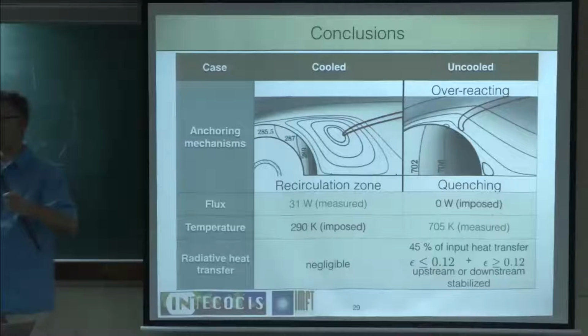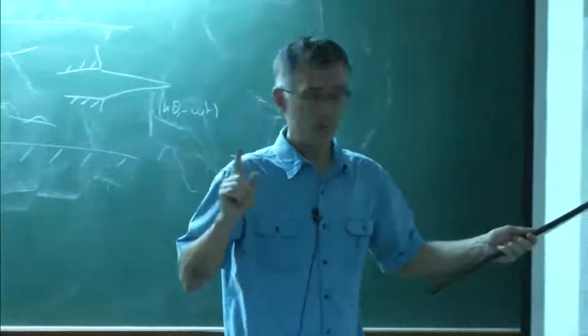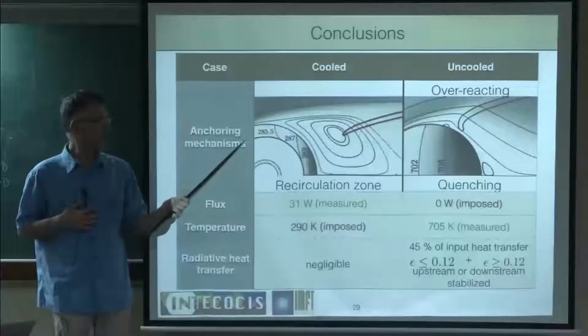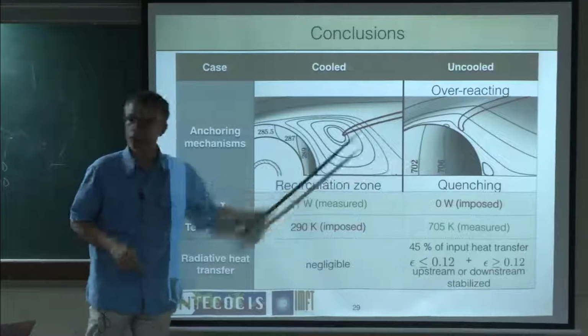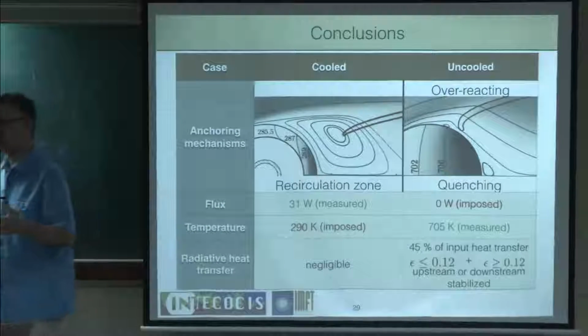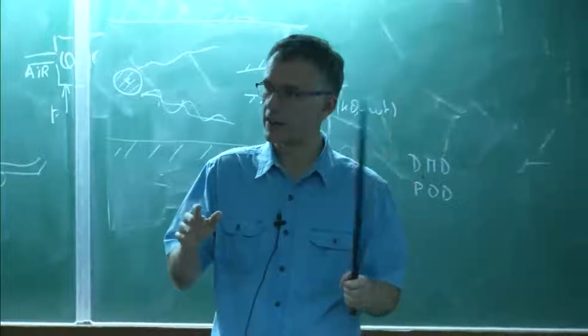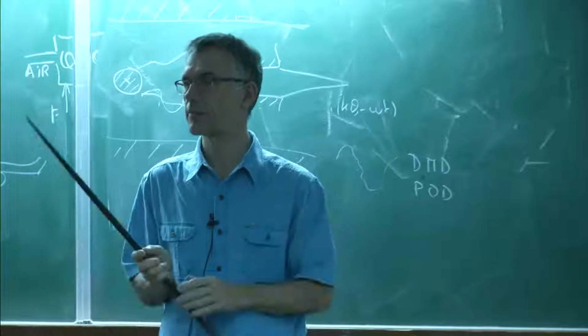Because the acoustic tuning is such that these two flames are stable. What's true, however, is that if their flame transfer functions are different, and you send an acoustic wave on this one, you have a different response from that one. That tells you that the unstable modes will also be different. But in this case, when we operated, we tuned the length of the combustor so that there is no instability.